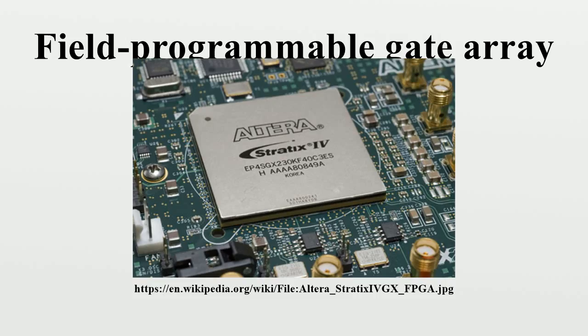Typically only FPGAs contain more complex embedded functions such as adders, multipliers, memory, and SerDes. Another common distinction is that CPLDs contain embedded flash to store their configuration, while FPGAs usually, but not always, require external non-volatile memory.